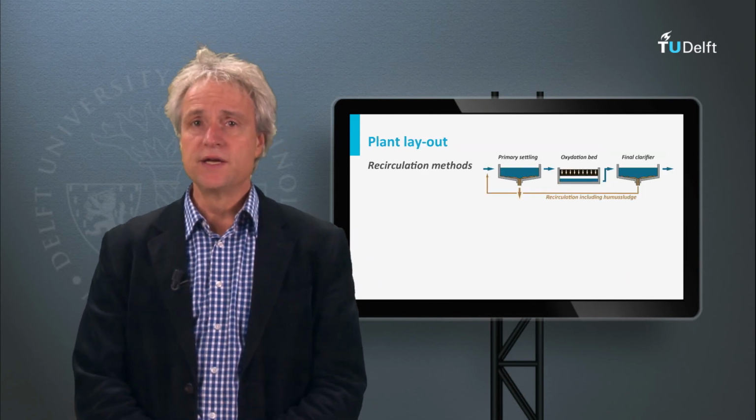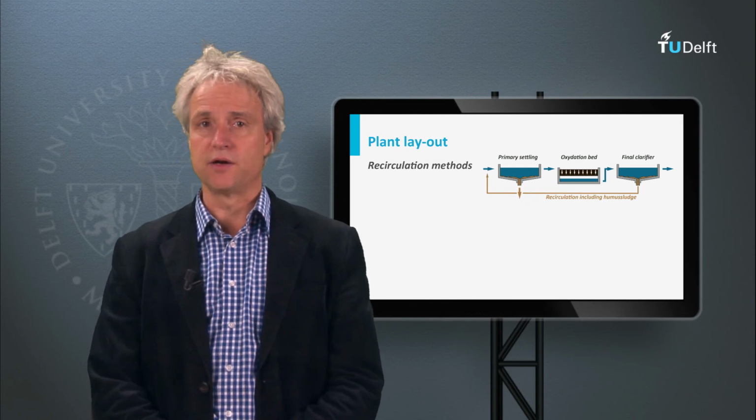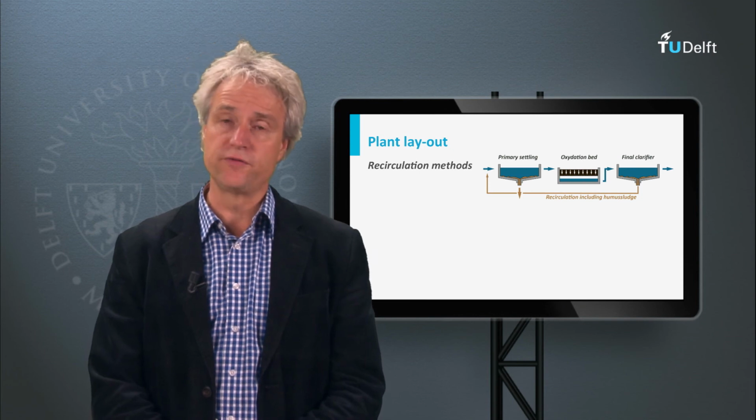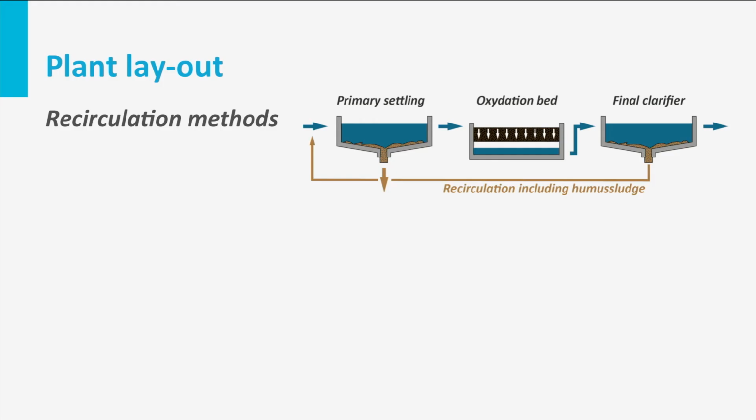A trickling filter is generally preceded by a primary clarifier to prevent the accumulation of solids and fats onto the filter bed. Excess sludge leaves the filter with the effluent and is retained in a secondary clarifier. As mentioned, the produced sludge is already partly stabilized, dependent on the applied BOD loading rate. From the secondary clarifier, often recycling is performed.